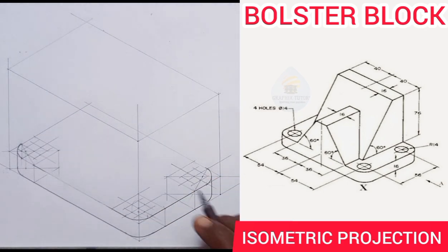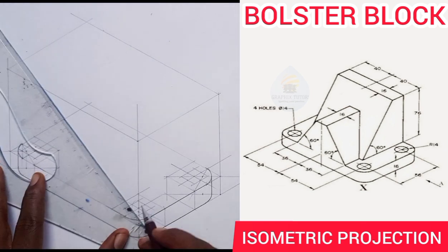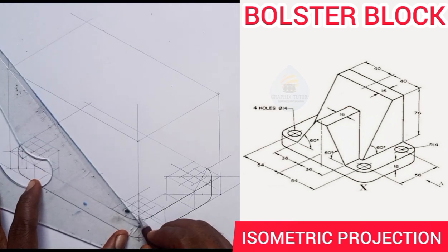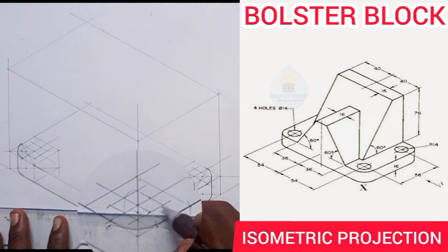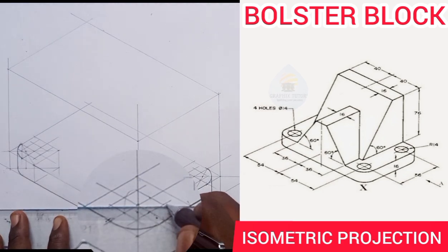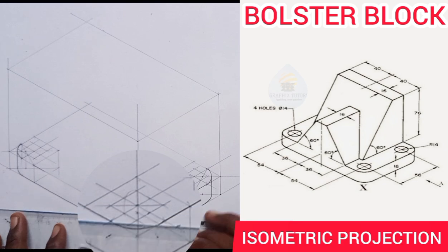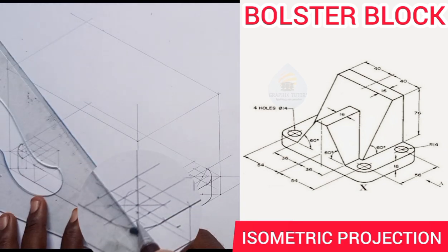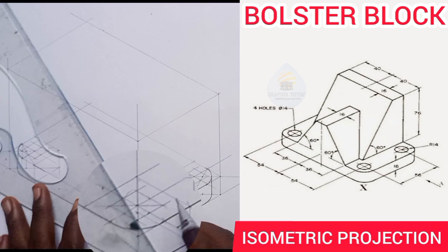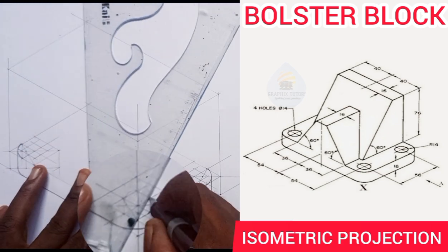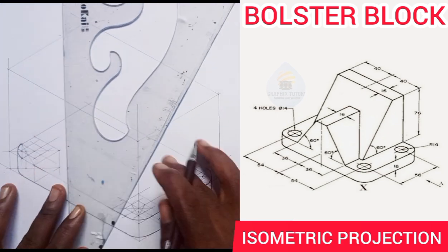This is where I'm going to draw in my circles. So what will you do? Just connect the shortest diagonals. This is the longest diagonal here. I should just draw it out the way I drew this. Right? So I'll now connect the shortest diagonal from here to this end. Using all this method we're using to draw circle is called ordinate method of construction.